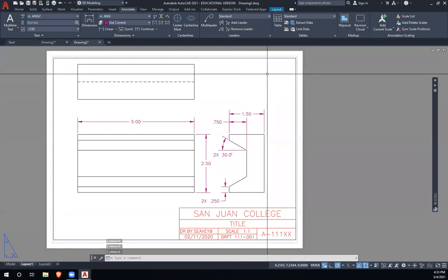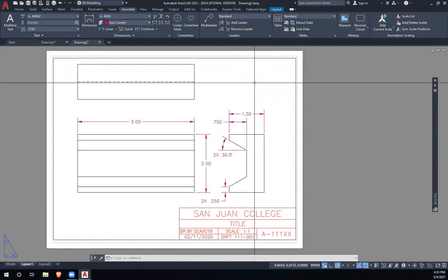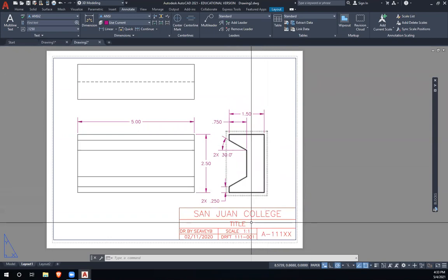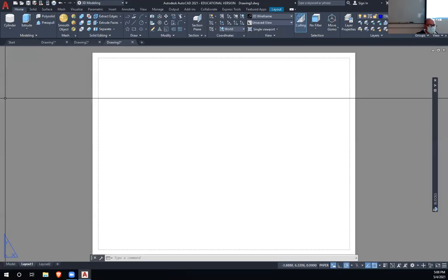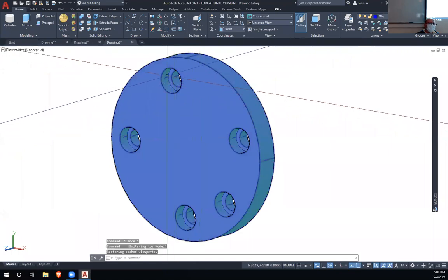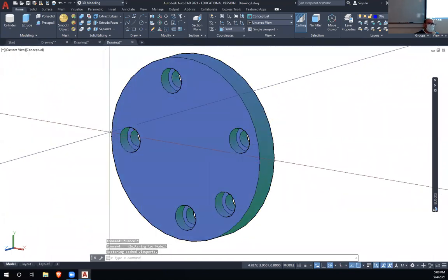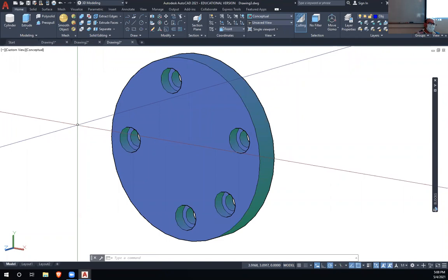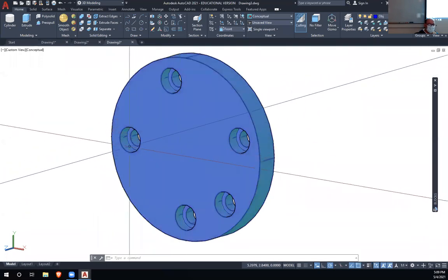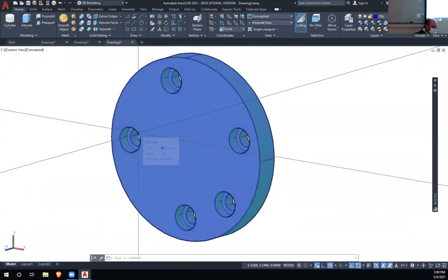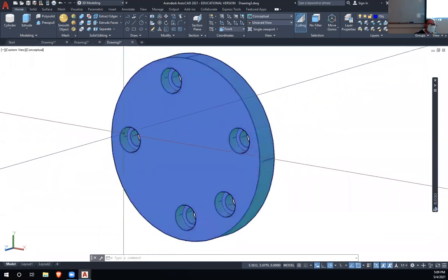So I've left out the little 3D view of it just because it's not necessary now. Okay, so yeah, we'll figure out what drawing number that is and the date and things like that. But yeah, this was a fun one. It really could be done in the front view where you could just draw the big circle and the one circle on the left, which was just aligned horizontally. So the through hole, which is 3/8 in diameter, and then the counterbore circle.